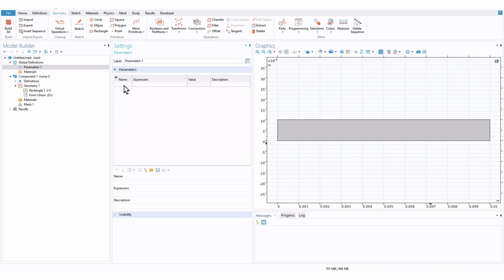At first we'll add the transition temperature. So we'll write T trans and this is 0. Okay. So we are writing in Celsius, so what we can do is write DEGC. Okay, that means that this is in degree Celsius and the value will be converted into Kelvin.